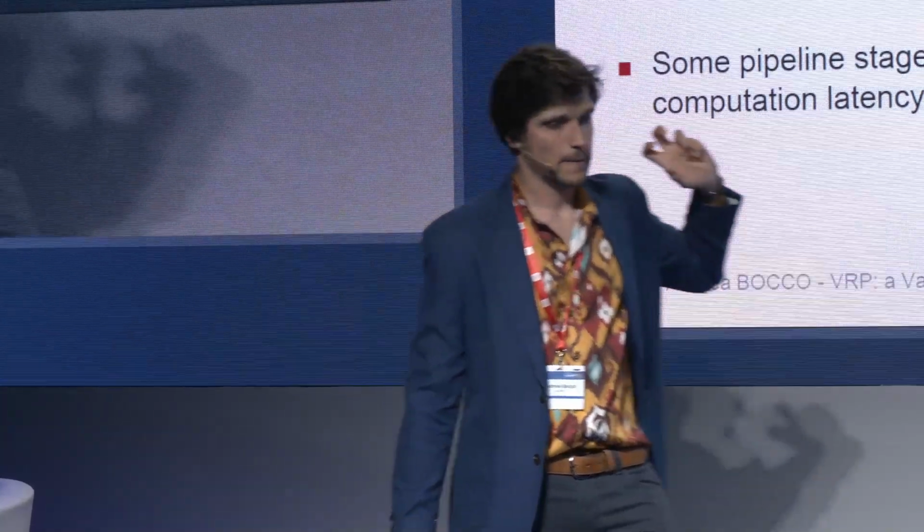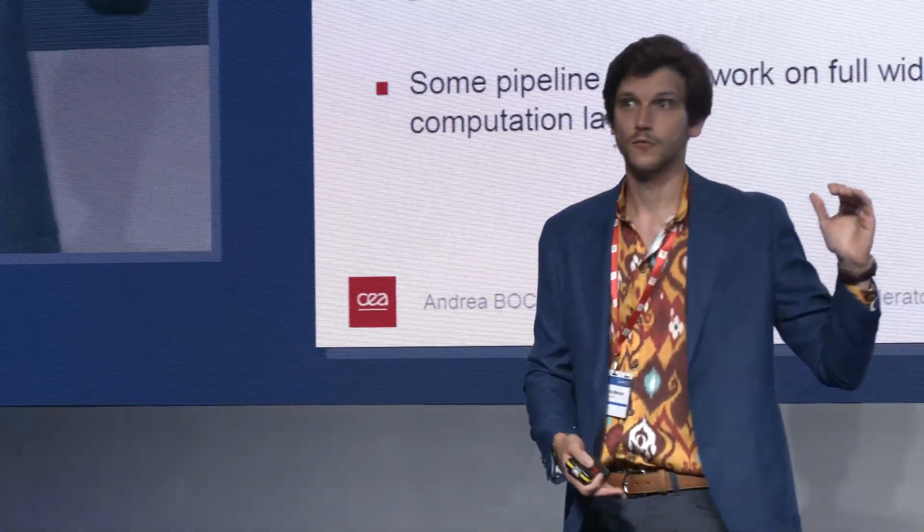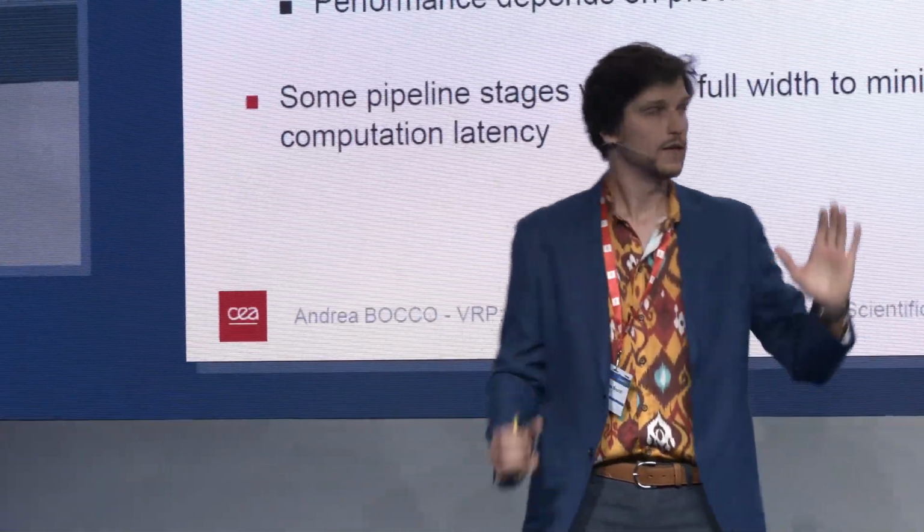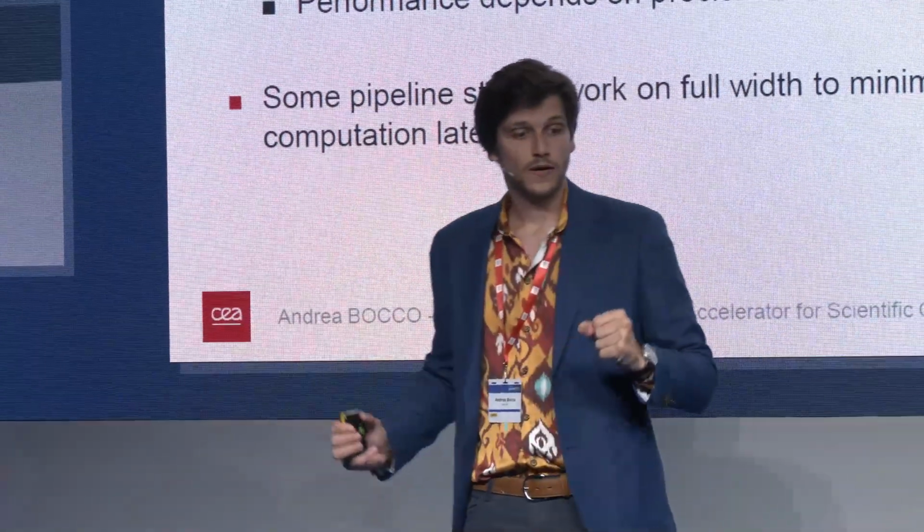What about the variable precision floating point unit? It's a floating point unit supporting the ISA that I showed you before. It supports iterative operations on the floating point mantissa. Why? We cannot have a hardware adder on 512 bits or a hardware multiplier on 512 bits, either. So we iterate on chunks of 64, 128, 512 bits, depending on the type of the integer operation that we want to do in every stage of our mantissa.